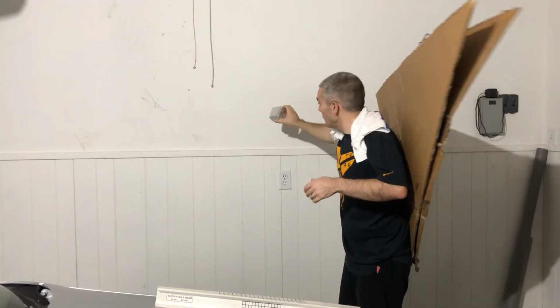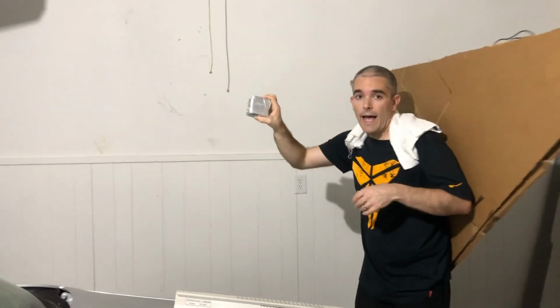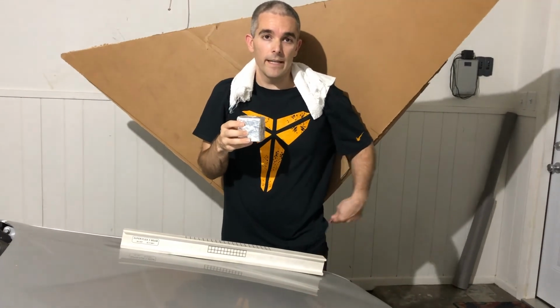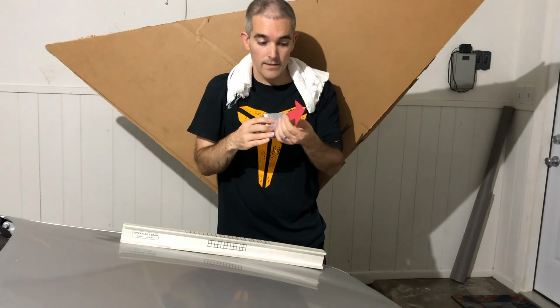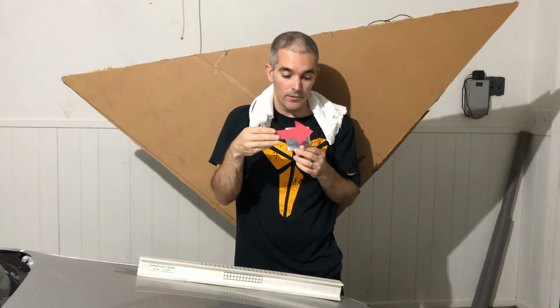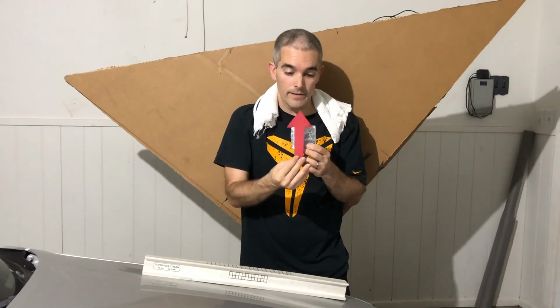So we see that when we pull this block or this element out of our wall, this surface has no stresses. Namely, there's no stresses on it in the normal direction, so acting out or pressing in on it. And there's also no shear stresses, so no tau zx or tau zy. Alright, so if we do that, we can reduce our general state of stress from 9 components down to 6 components. This applies to many situations.